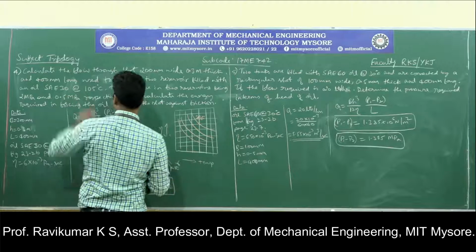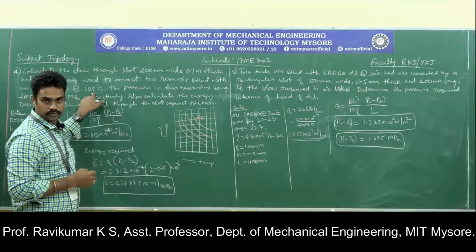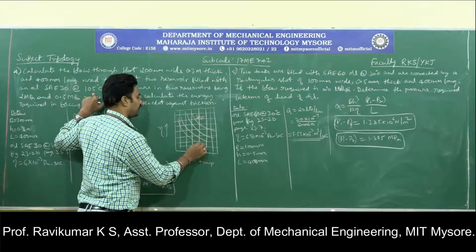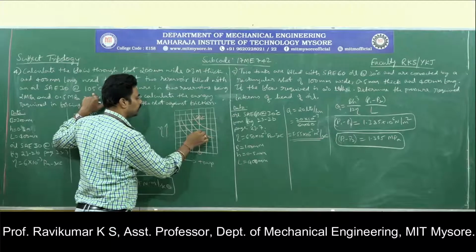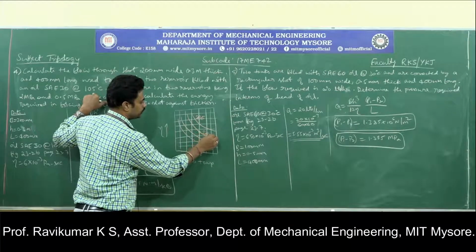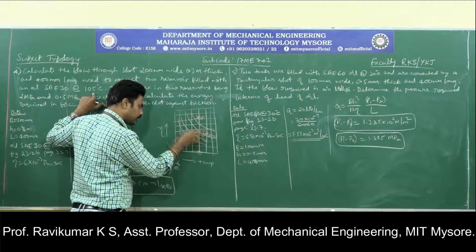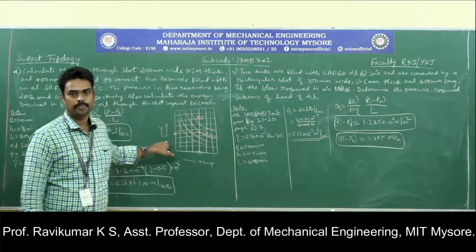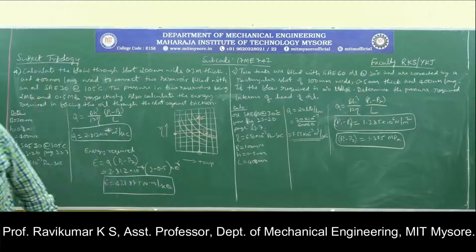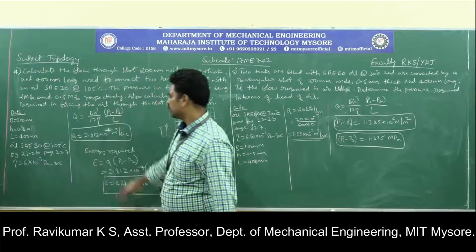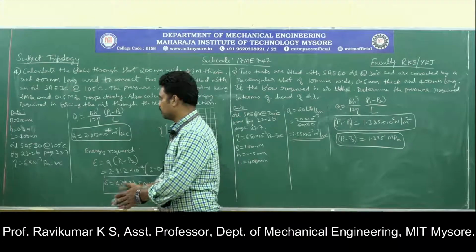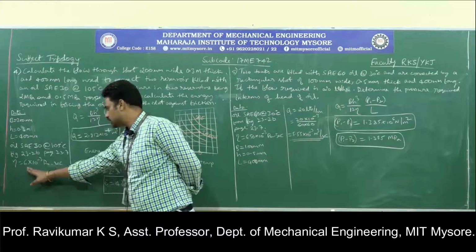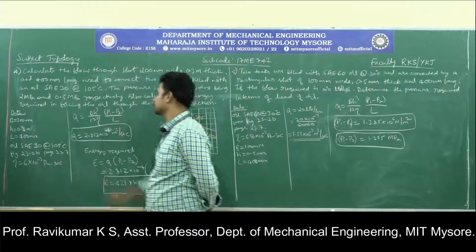Here the temperature is given as 105 degrees Celsius. So go to temperature 105 degrees Celsius and climb up until you meet the SAE 30 curve. Then go to the y-axis to get the absolute viscosity, eta. This is how I need to get the absolute viscosity. It is exactly like the stress concentration chart; you have studied that in design. So from the data handbook you can obtain viscosity as 6 into 10 power minus 3 Pascal second.